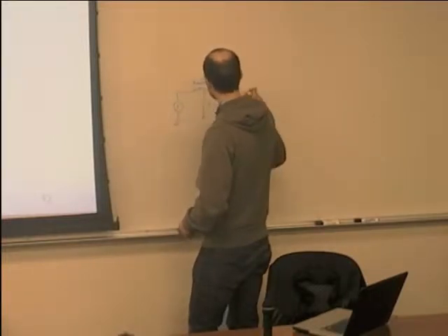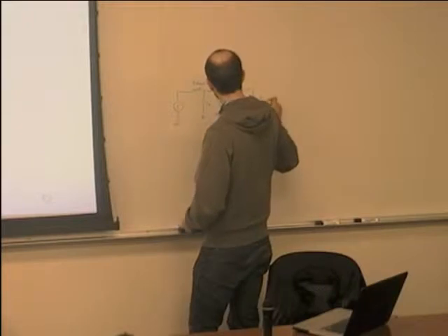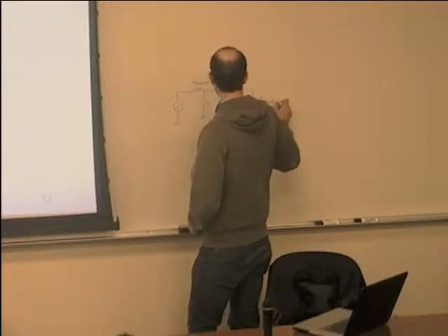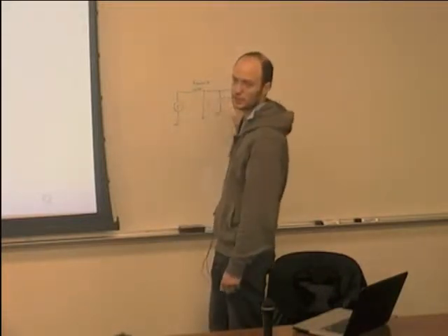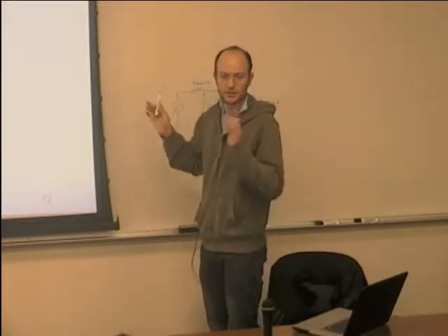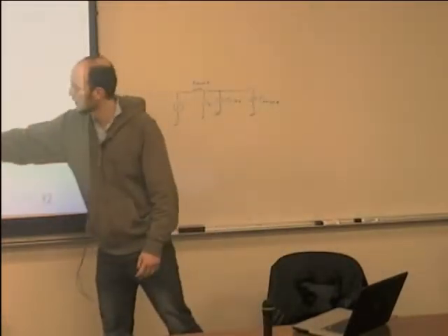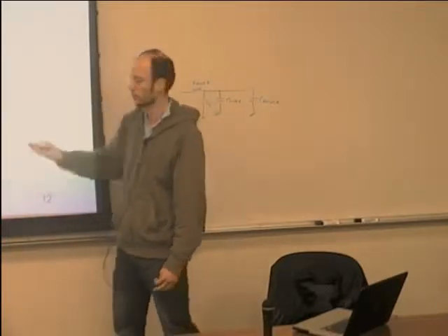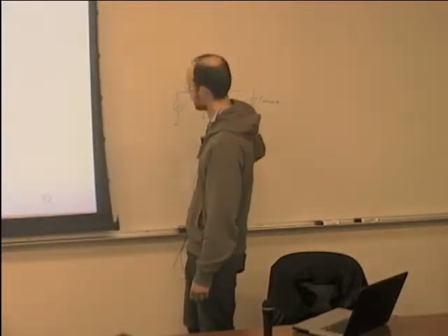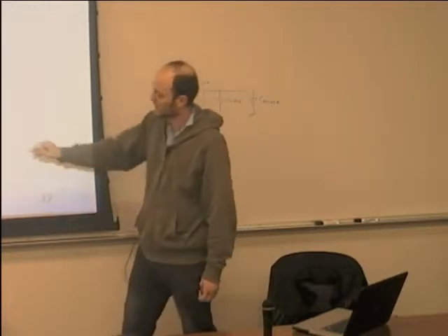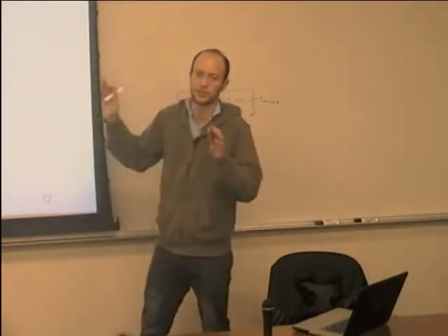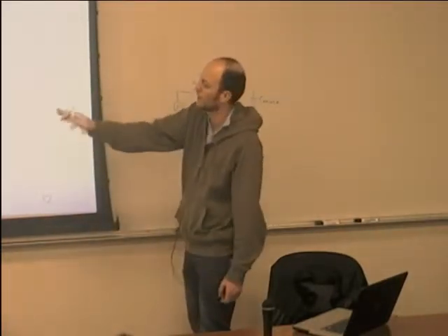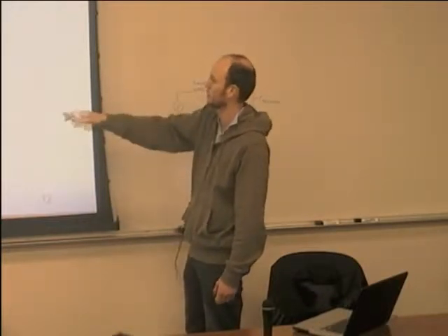Okay, we are ignoring the load capacitance, but these are easy to include, right? Because we just add them in parallel, and they change this capacitance. If this wire is big, this capacitance will be larger, but it will only change by a little bit. In any case, you just add them and you're done. Instead of having R driver C lump, you have R driver times C lump plus C load.